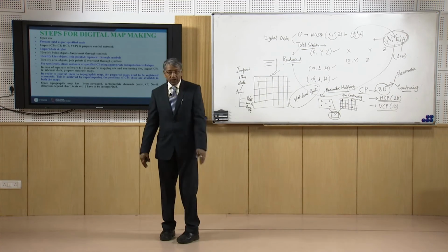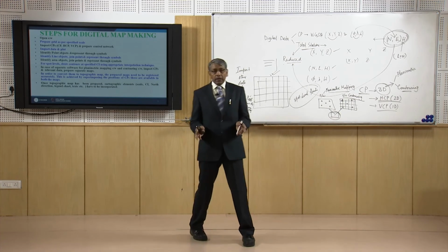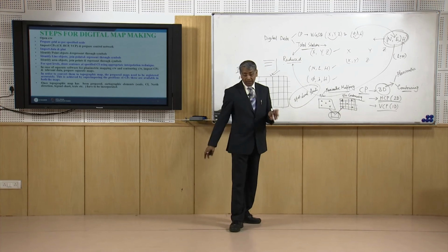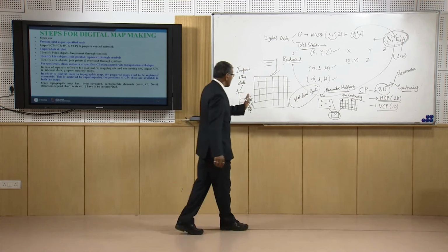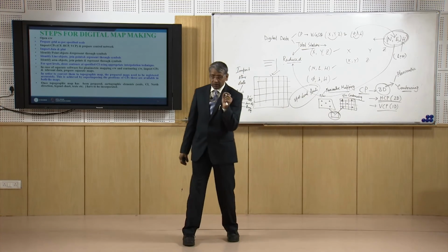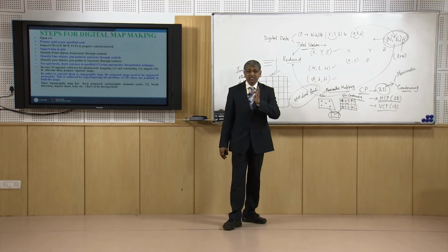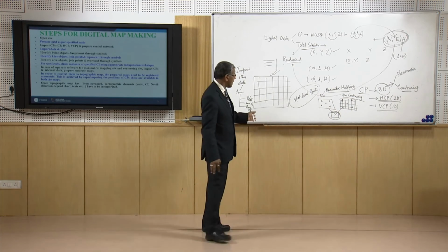This is the most important, and next important is the contour interval. One thing has to be noted: in a particular map the contour interval is constant. So, the contour interval also has to be noted down in the map. Another important feature of a topographic map is the direction of the north. So, the north direction has to be noted down in the map.